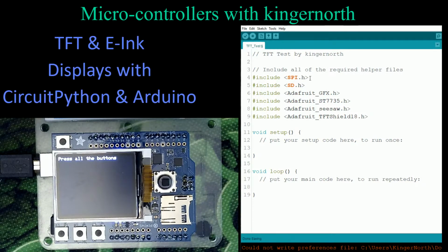So it's pre-using some of the pins that are out here for this, and it's allowing us to set that up. There is an SD card on here, so if you want to add more graphics, something that the Arduino Uno does not have is a lot of memory. So you may not have the ability to include bitmap files and save them. Well, you can put them onto an SD card, put them in here, and then call them up and buffer them and then display them. So including SD.h will allow you to access the SD card.